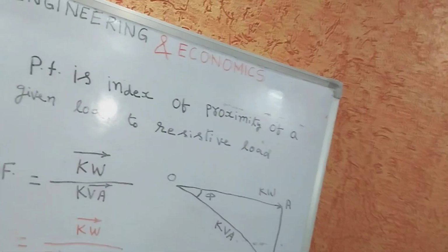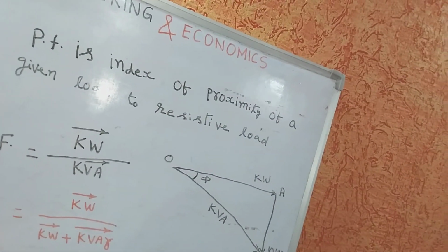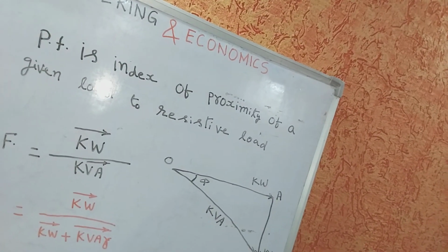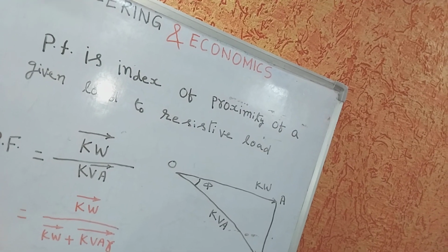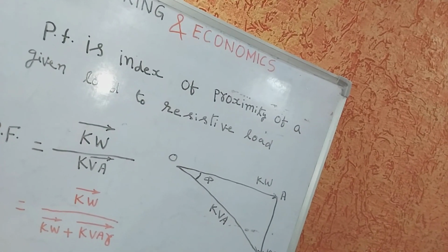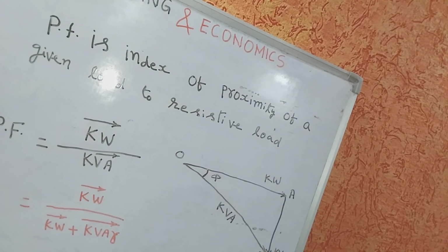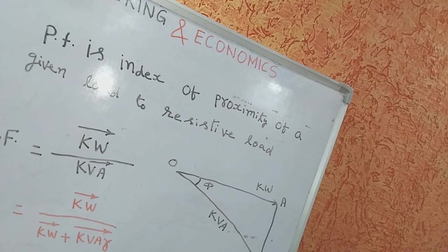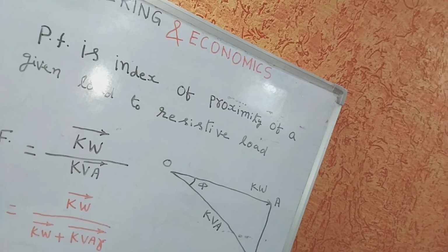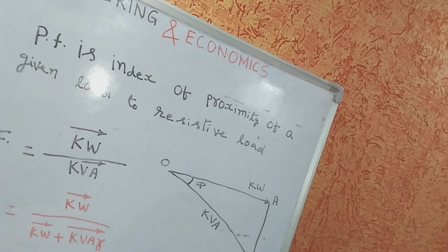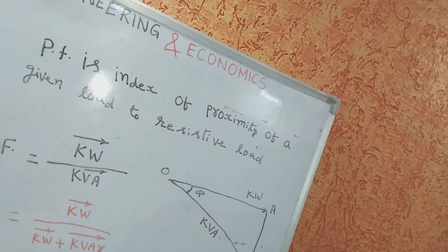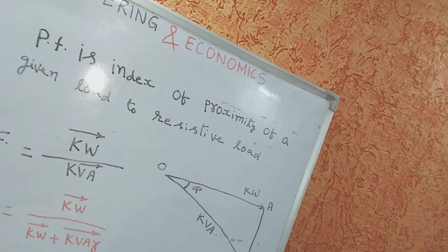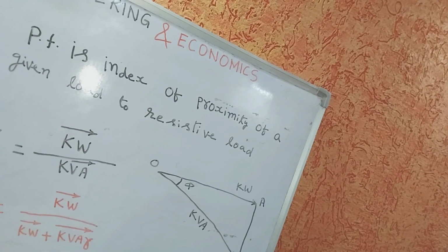When input is given to a stator, it creates a rotating magnetic field in the air gap between stator and rotor. The induction motor therefore must operate at a lagging power factor. This power factor is very low at no load and increases to about 85 to 90% at full load. So even at full load, power factor correction is required.